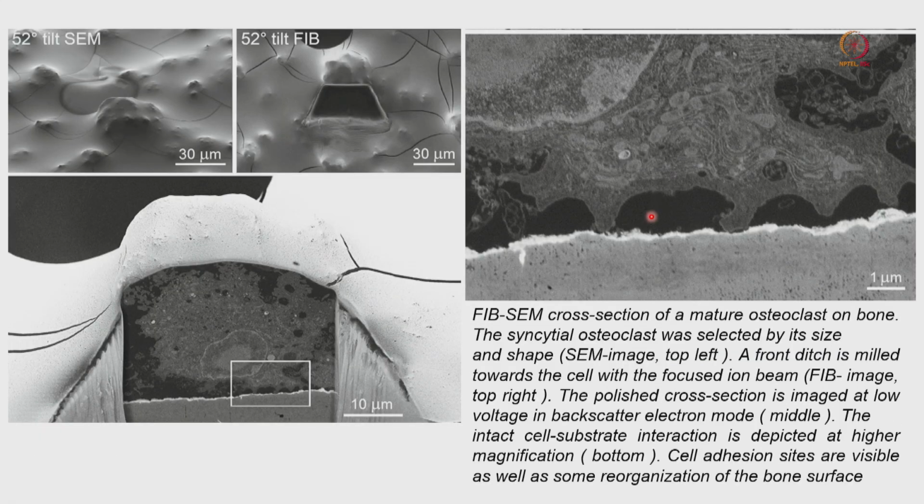So, I will directly go to one example where you can see it. Here you can see this is our SEM. We are targeting this particular area. This is my area of interest that I want to focus on. Then I am using that 50° tilt FIB, that focused ion beam. So, this is our 50° tilt SEM image. This is the target area. Then I am using the 50° tilt FIB image, and we are trying to open, forming a small window here.